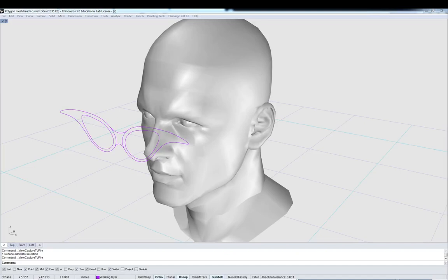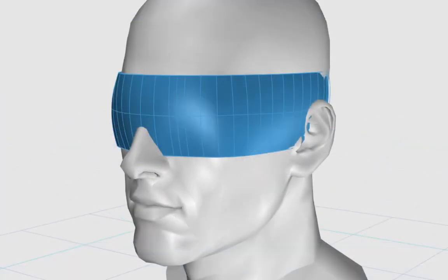In this tutorial, we're going to make this surface. And that surface is what we're going to use to project these curves that we built out on front onto. That way we'll get three-dimensional curves that we'll build our two-rail sweep from. So let's get started on that.